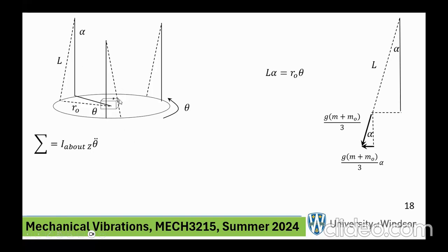That means the gadget that we want to know something about, and the disk in the vertical direction, theta double dot. Okay. So let's see. Remember, what I left out here, unfortunately, is the sum of all the moments about the mass center. And where are these moments coming from? Well, it's coming from the tangential component of the tension.